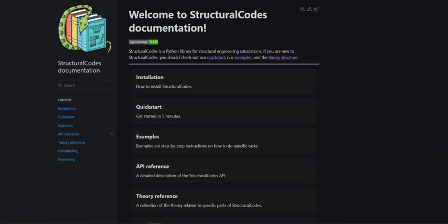So something that wraps the geometry, the material, and adds methods or attributes to it so that we can integrate strain response over the cross section, and with different method calls for doing different types of calculations. So in this block at the bottom here, we call what we call a section calculator to calculate the moment curvature relation.